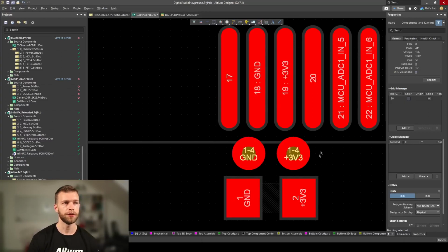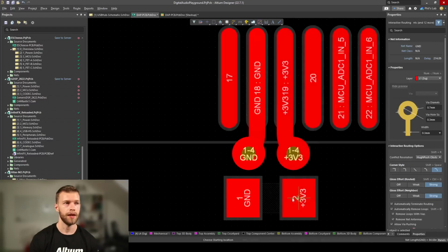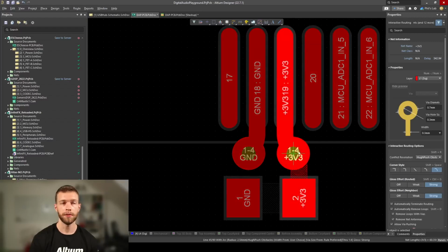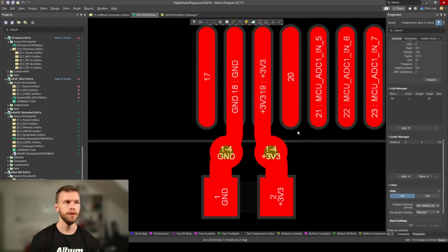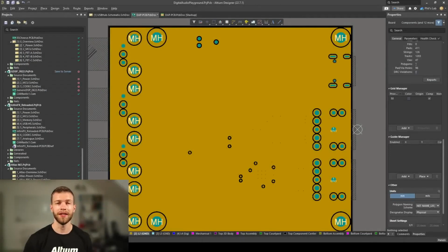Keep in mind, I've also tried to keep clearance between the vias and any other non-related pads. Then I can simply route out with a trace that's as wide as the IC pad into the via on both sides, and then use thick traces from the decoupling capacitor pads into the vias. For example, like so. Having closely spaced vias minimizes inductance. We've placed our decoupling capacitor very close to the IC pins, but still given us space to route out the relevant microcontroller pins.